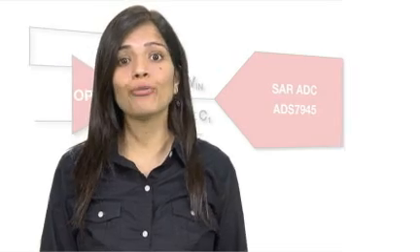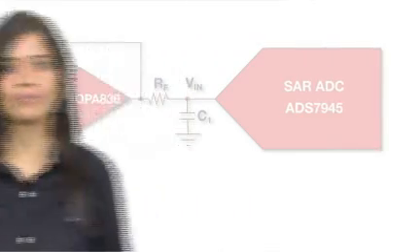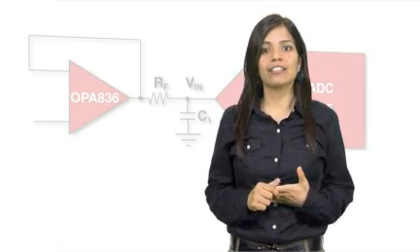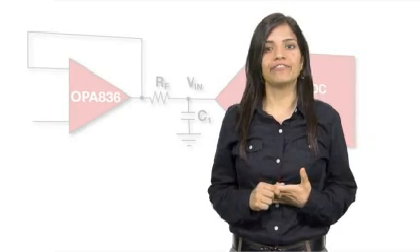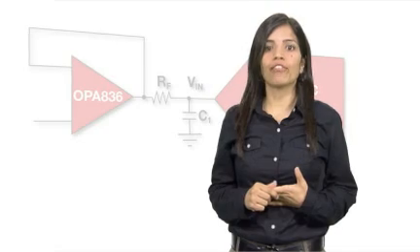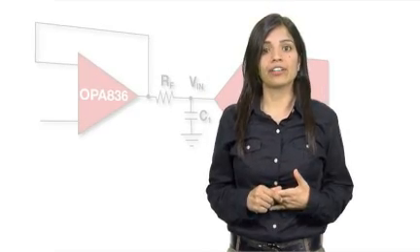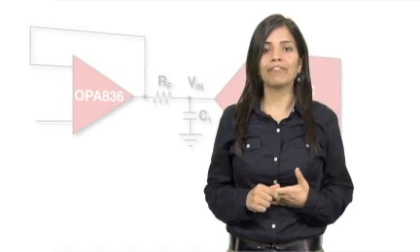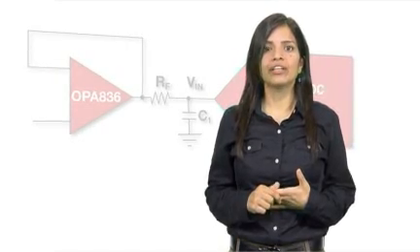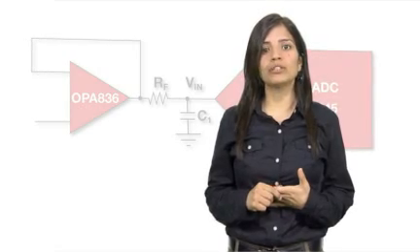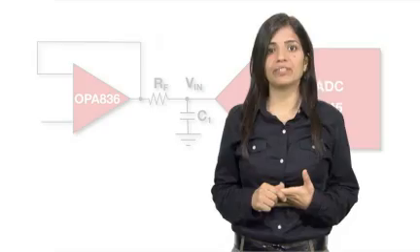Today, we are going to show how we can achieve the specified datasheet performance for a SAR ADC driver when driven by the right operational amplifier. For optimum SAR ADC performance, the recommended driving circuit is an op-amp in combination with an RC filter. Without proper selection of the RF and CF values, the circuit could produce ADC conversion errors, or worse yet, cause the amplifier to be marginally stable. You can run into amplifier stability issues if you ignore the op-amp open-loop output impedance and gain bandwidth product.